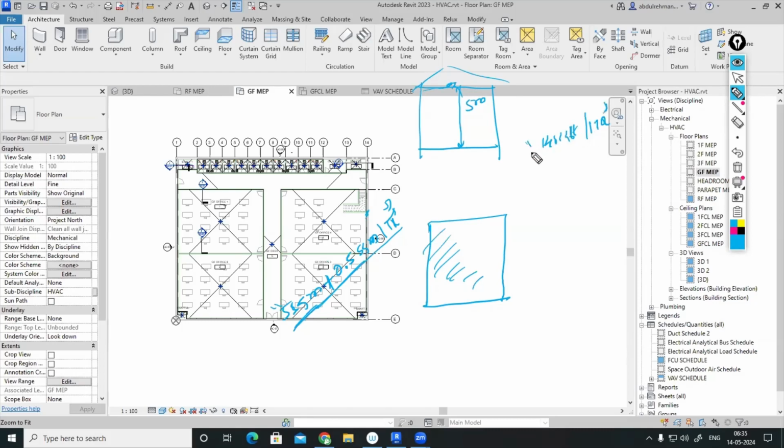But as you know, how to do the heating and cooling load calculation using HAP software, or by the E20 sheet, that we have already studied. But once the project is starting, sometimes the architect might ask, okay, what is the minimum dimension that you require for a plant room? Accordingly, only they will consider the space for this plant room. So once the project is starting, we might not have that much time to do the heat load and all. So roughly, we have to give the floor area data to the architect. Accordingly, they will make it.